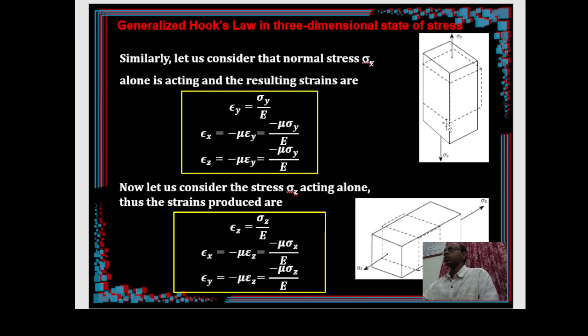They are all giving longitudinal, axial strains, and in the other two directions you will be getting the lateral strains. Because there is extension in the y direction, the other two directions get contracted. That means if this is the depth direction, the length and width directions will become contracted. Now here epsilon y can be calculated directly from Hooke's law, because the stress is acting in that direction, so the strain can be calculated with the help of Young's modulus, right?